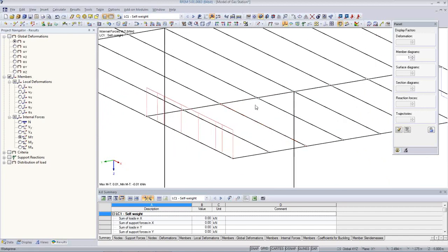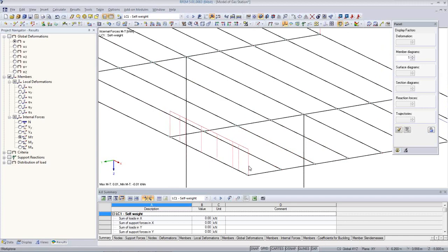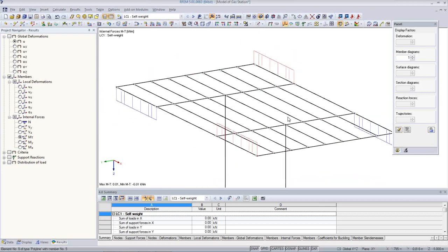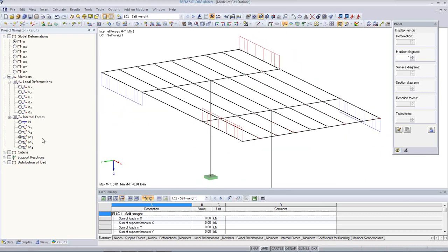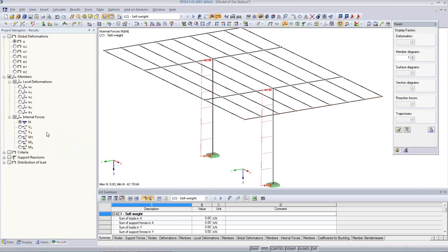So it's really a scissor type hinge. We have a minor, very small torsional moment due to this connection here, which we can really neglect. And it seems to be symmetrical, so everything seems to be all right. We have axial forces, so everything seems to be reasonable.